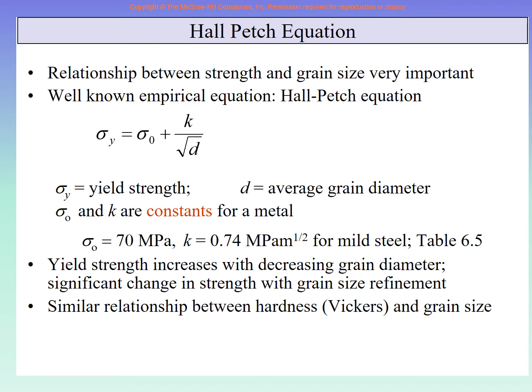So you see, remember when we were talking of the effect of grain size on the strength of a material earlier, then we told you that if we reduce the grain size, if you have fine grains in the material, then there are lots of grain boundaries, isn't it? If the grain size is large, then there will be a few grains, so the boundaries between the grains will be a few.